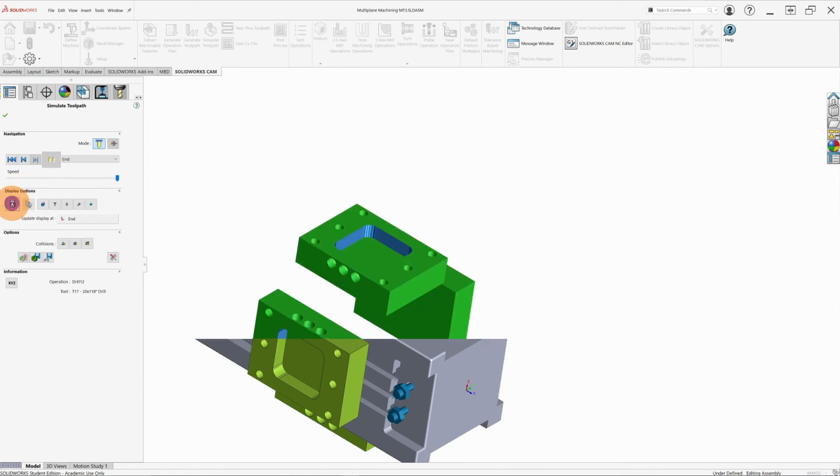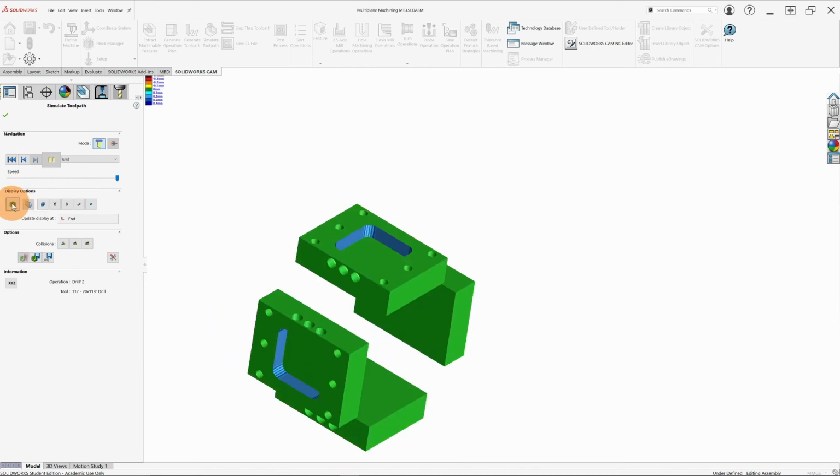We'll just take a look at the show differences. So everything is fine. This here is blue on the inside because we're using that roughing operation and we're not going back and contouring it. But that's fine for this particular piece. That's the tolerance we were looking for.